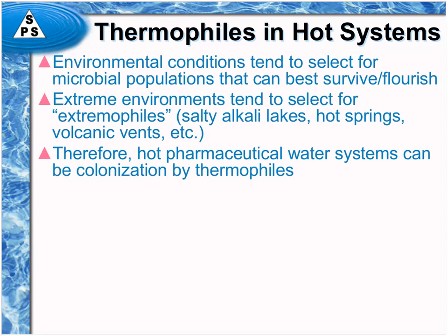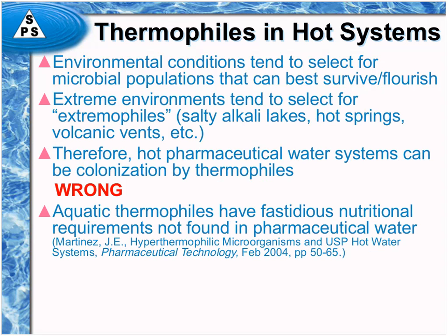Therefore, one might expect that a hot pharmaceutical water system would select for colonization by thermophiles, but that's wrong. It doesn't. Why doesn't it? Because all the aquatic thermophiles that are known to exist have very fastidious, exacting nutritional requirements that are not found in pharmaceutical water.